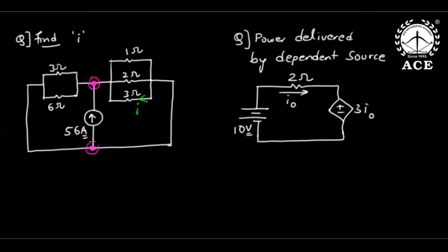And here also, what is the degree of this node? Don't just see this 3 and declare. You see these 2 are parallel: 1, 2, this current source 3, and these 3 parallel make 6. So this is a single node with degree 6. This is another single node, or principal node, with degree 6. There are only 2 nodes. Actually, all are parallel, sir. Between these 2 nodes, all branches are parallel.